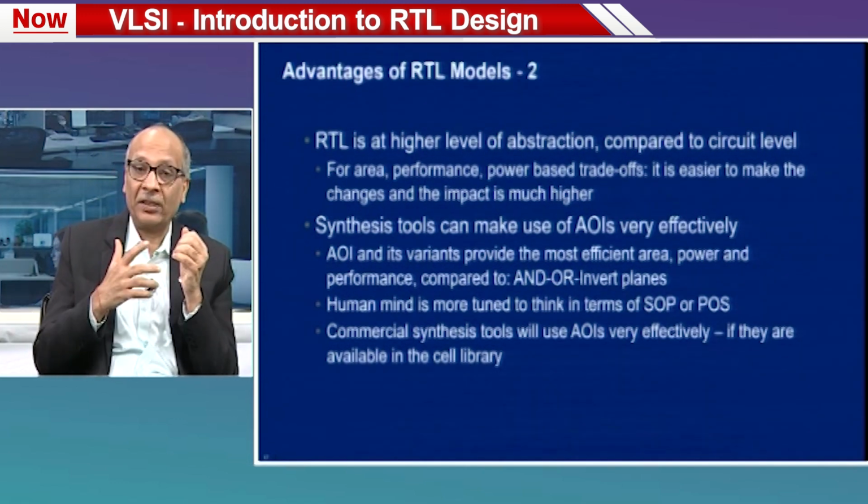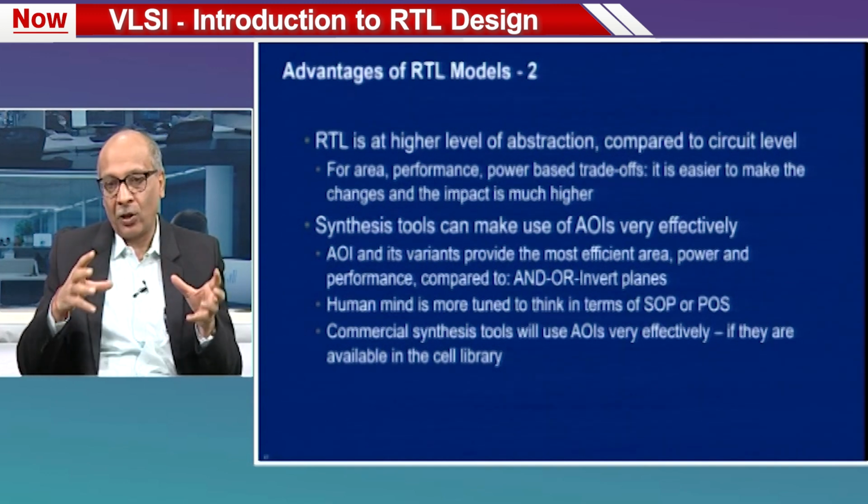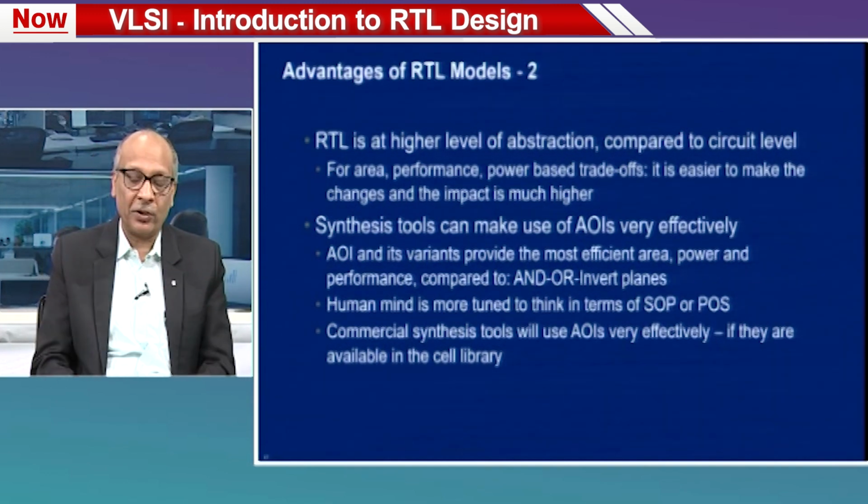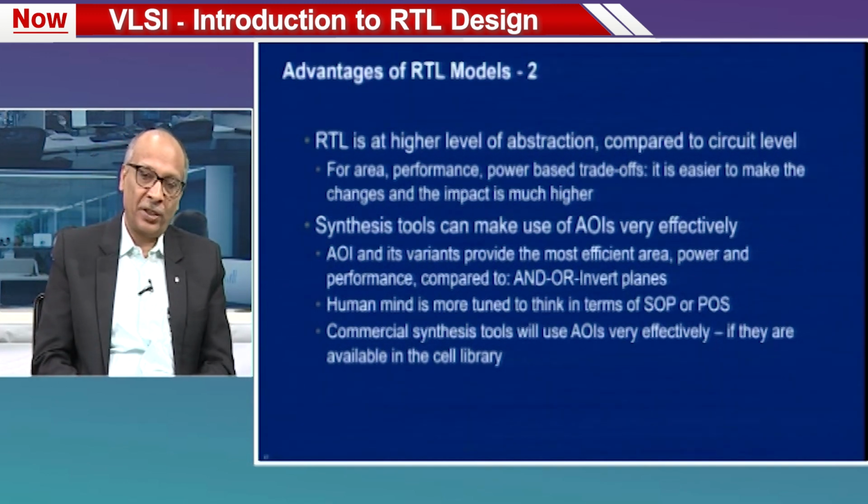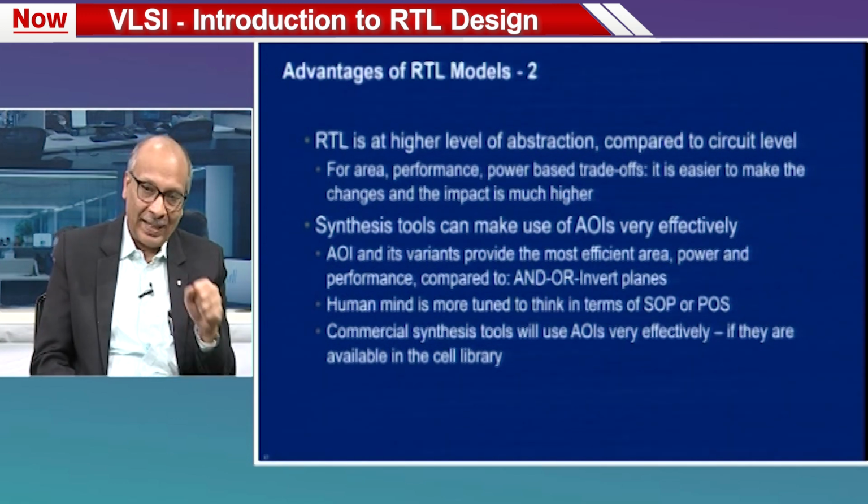In fact, if you have to realize any digital logic, try thinking of realizing it in terms of AND-OR-invert. It is not easy to think of it. It is much easier for us to think in terms of AND gate separately, OR gate separately, inverter separately, or you could do NAND and OR. That is also okay to realize with some practice. But thinking of AND-OR-invert based expressions is not so easy for the human mind, while a synthesis tool can do it. So, effectively, if you write RTL and go through a synthesis tool, we can get designs faster, and the circuit is also much more efficient.